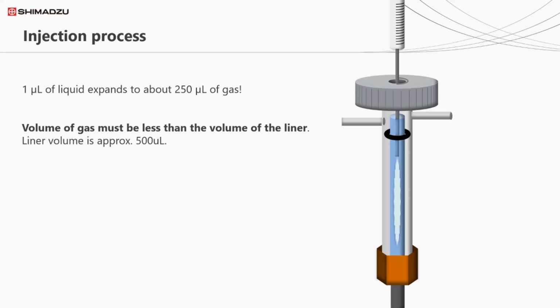If, or when this happens, the sample cloud expands into whatever space it can find. This means that, as well as going onto the column, it can travel down your septum purge line, and even back up the pipe supplying your carrier gas flow from the controller. This is what's known as backflash, the flash vaporization of a solvent down pipes and tubes connected to the inlet